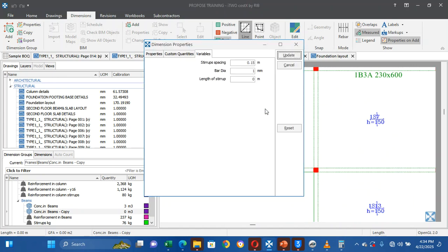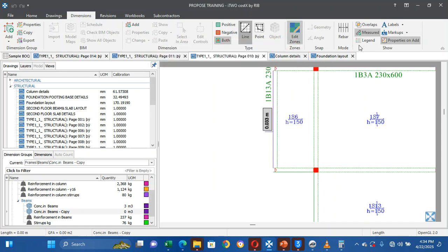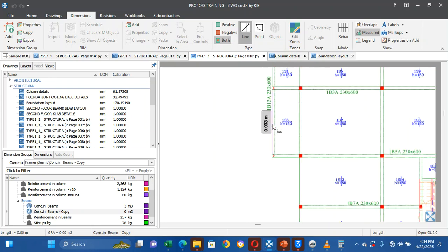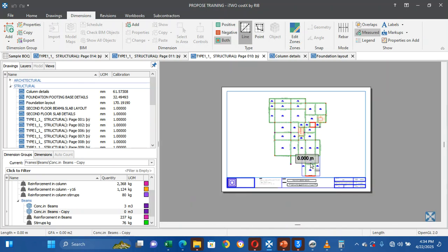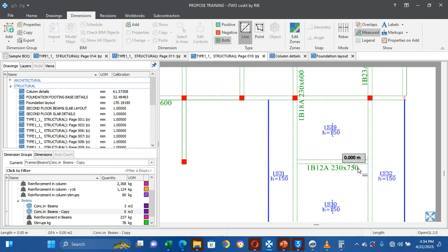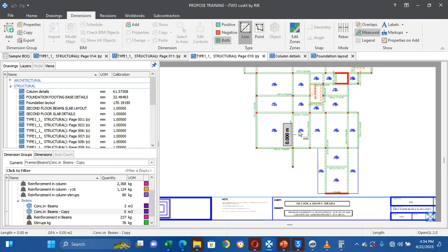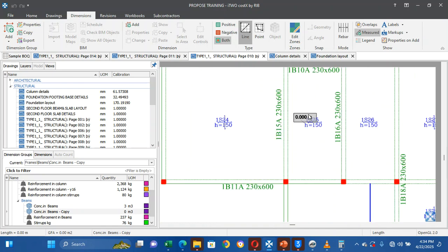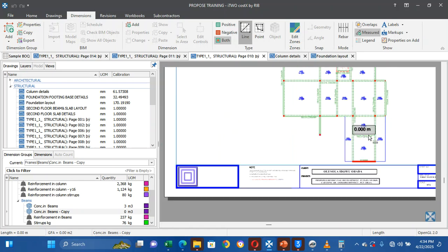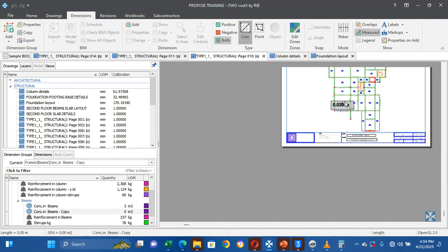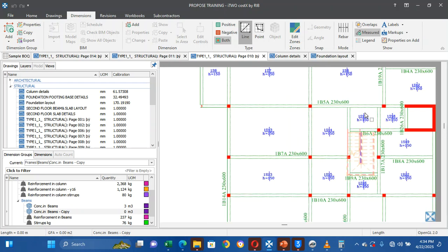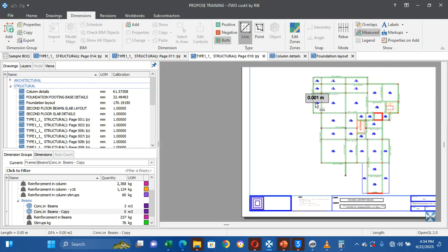It's my first line. Sorry, let me turn this off, because what I'm just looking for here is just the depth. We know that we can check all the beams; the depth of the beams are all 600. Check it. Okay, this one here is 750. This one here is 750. So we'll combine the ones of 600. When we come to this aspect, we'll change it to 750. I think that's the only place we have 750. Okay, so I'll keep that in mind.